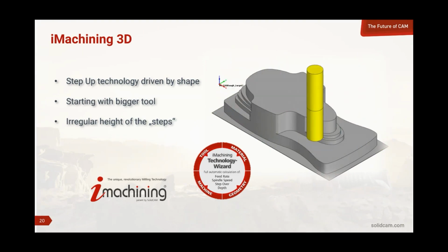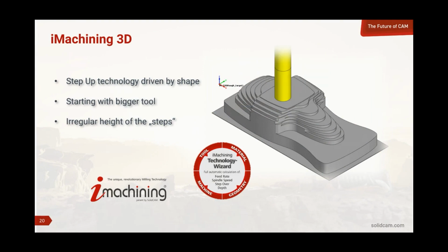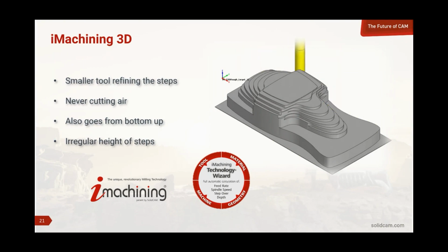This is how it works if you want to watch this through. So we took the deep roughing pass, then we're coming back and staircasing it up, and then we can go back to our rest machining. As you can see, this is a fairly coarse strategy here. But now we come in with another operation and we begin to reduce each of those individual staircases even more, getting that smaller tool in tighter to those internal corners where the bigger tool didn't fit all the way in. And we have two things going on at once. We're continuing that roughing process, we're clearing out the smaller corners, and of course, we're also creating that near net finish.